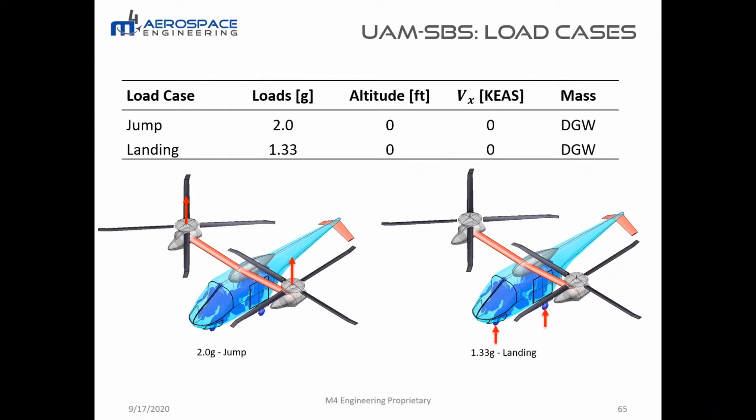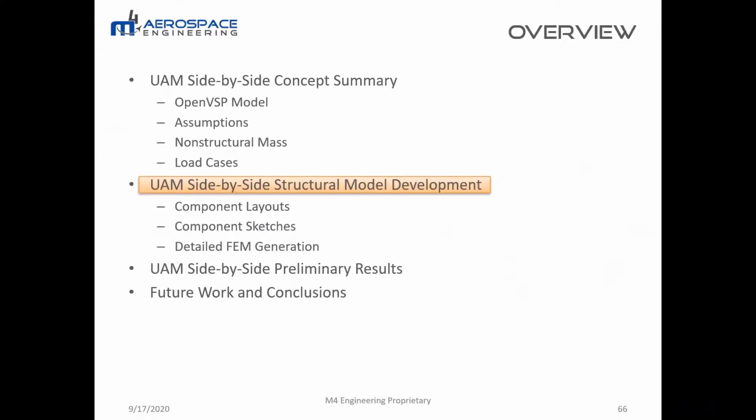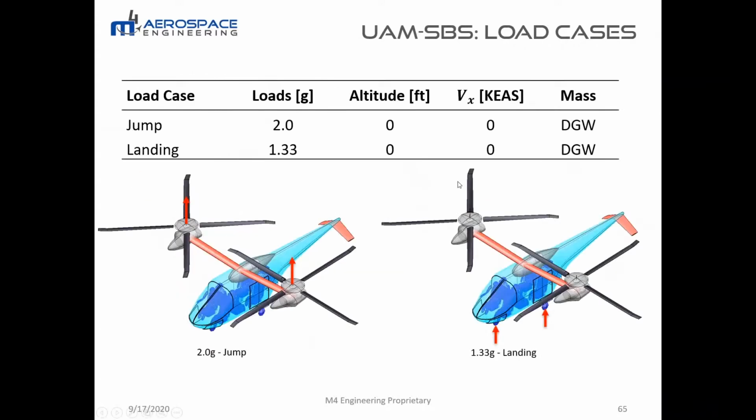So on a configuration like this, the wing and the tail keep moving, they don't have very large areas, and so we don't expect a pull-up type maneuver to be very significant for the structure. If you're looking at something like a tilt rotor, that's definitely something to keep in mind. You can use both of these helicopter type load cases and aero trim cases, like a pull-up or a pushover type maneuver.